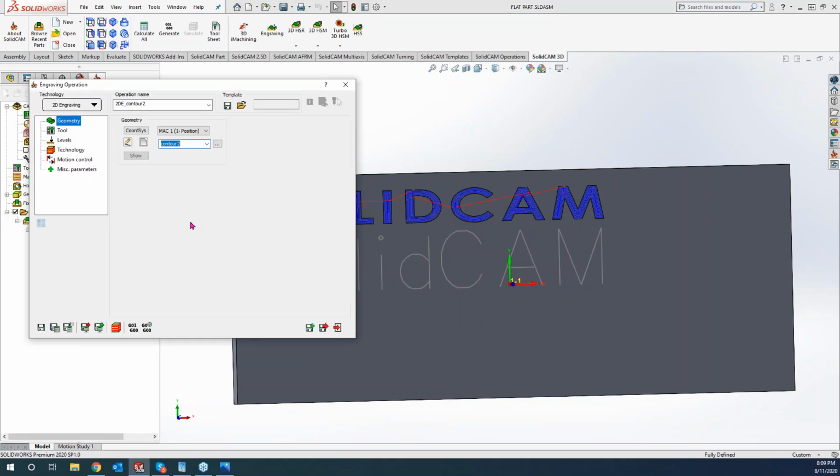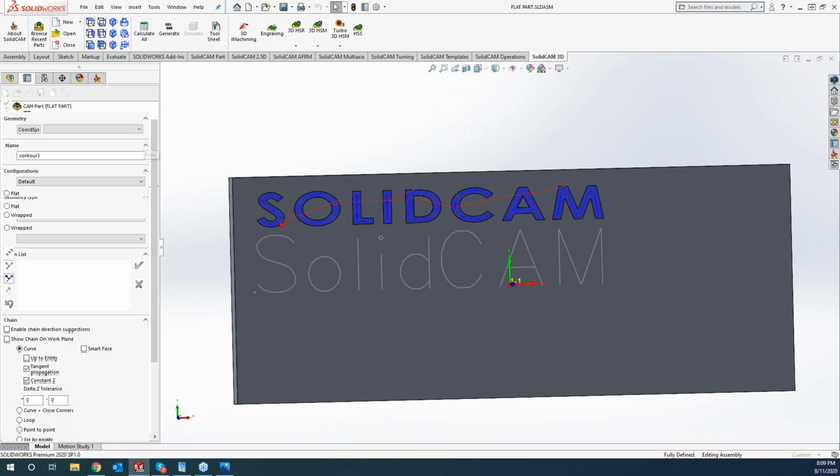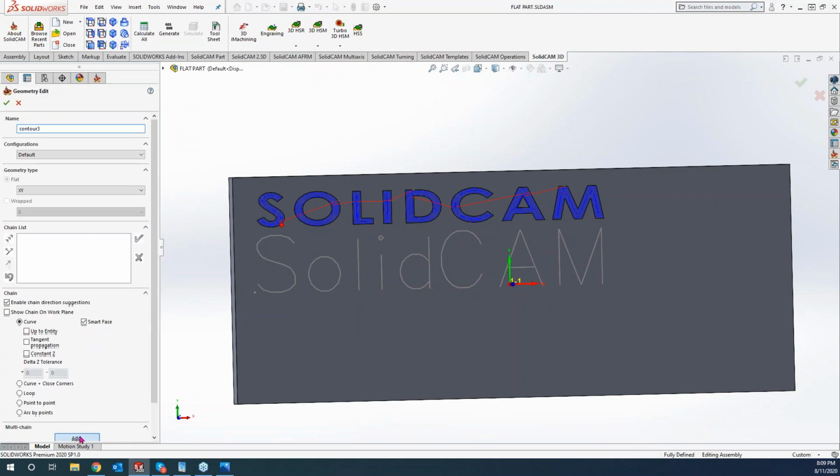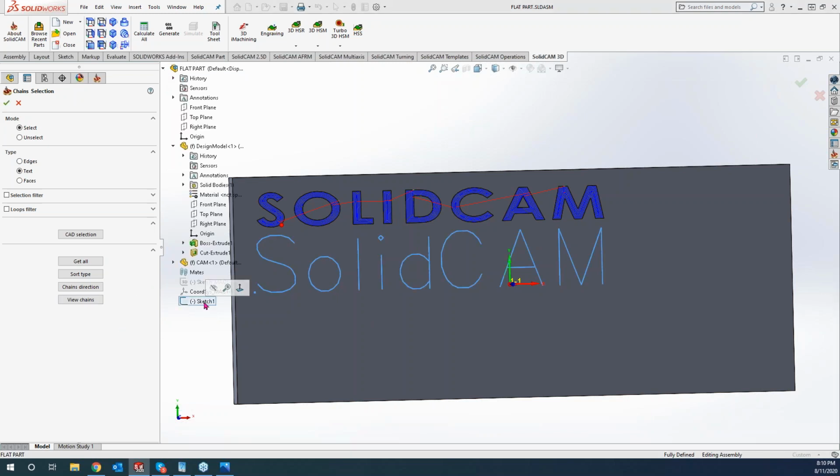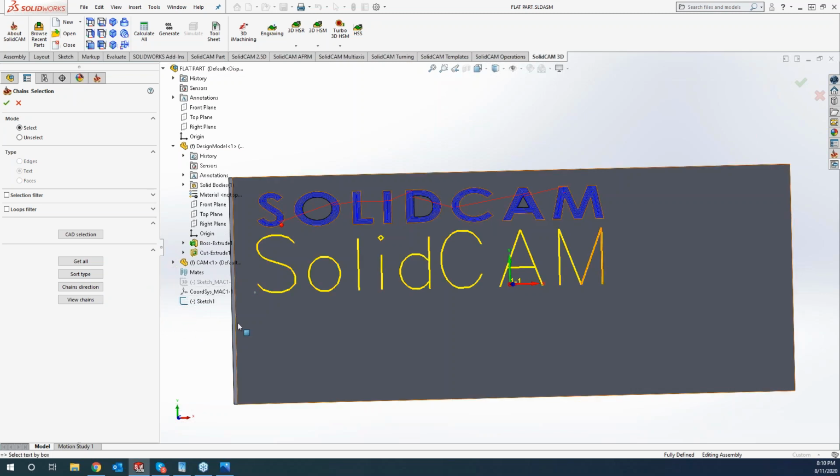Now, another way of going about it is come in here, do new, and we can go to our multi-chain. And this is if you were to have multiple different texts, but maybe you want this one right here, maybe a 5 thou, and maybe a different text at different depths. So you can come through and kind of cherry pick what you want. So we can go to text, and I can come down to my sketch and grab it that way. So if I had multiple different sketches in there, I could grab those at the same time also. So a couple different options for you guys.